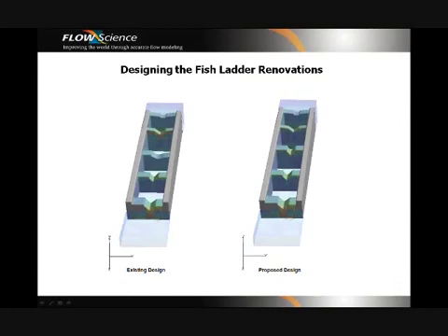Based on the Flow3D results of the existing design, changes were made to provide an easily navigable passage for the fish. The middle weir was designed to maintain the asymmetrical shape of the two downstream weirs, and its elevation was increased to equalize the hydraulic drop between them and the upstream weirs.